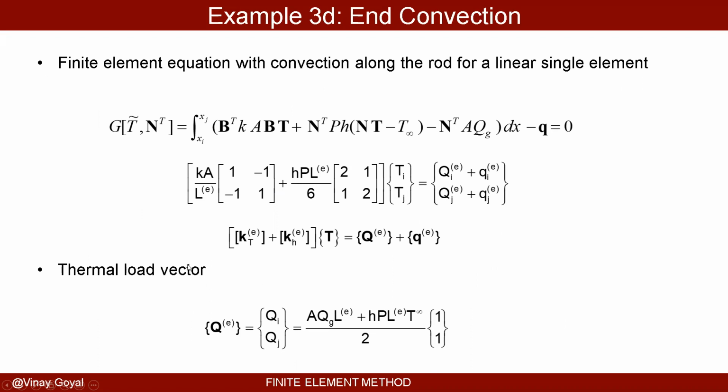The thermal load vector for a uniformly applied heat load Q is going to look very simple, like that. Remember that M bold h T infinity goes to the right-hand side, and that's what is showing up here on the right-hand side.